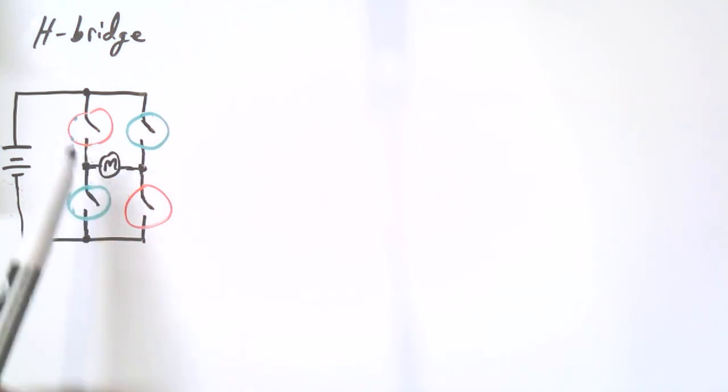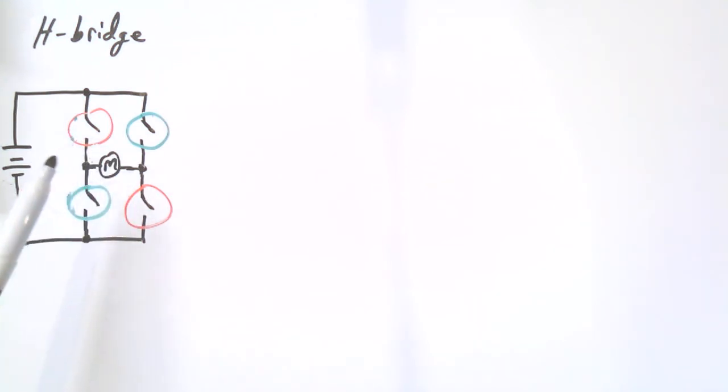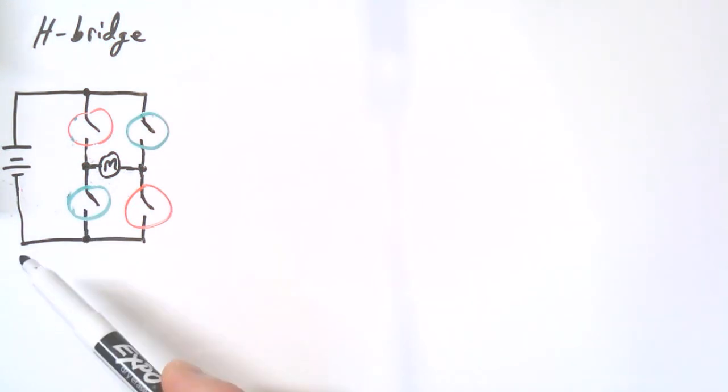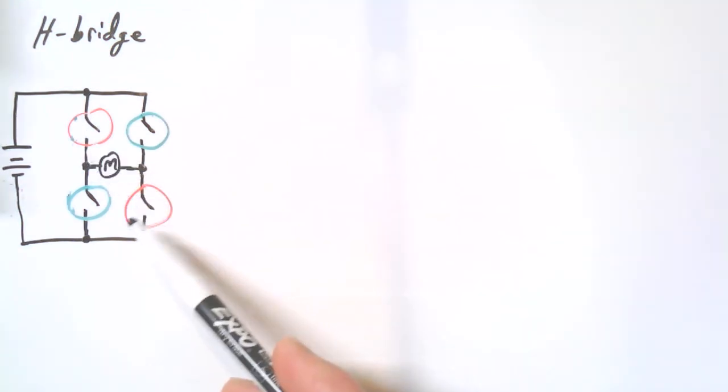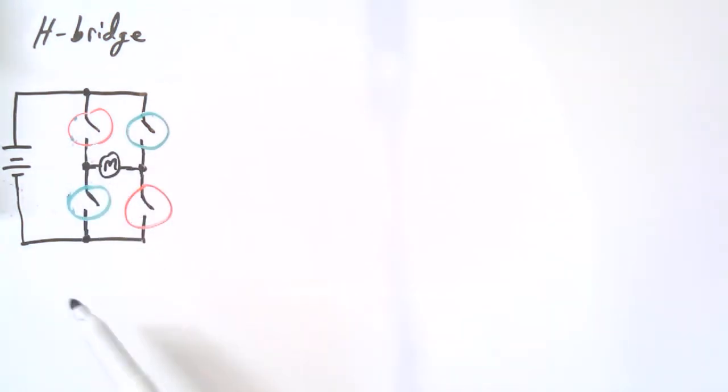But the red circle, don't let that get stuck in your head and reach for red contacts, because the standard, when you get to industrial switches, is that the red contacts are normally closed. So that's just a little heads up. It's something I've seen in the past. Those aren't red contacts. They'll all be green contacts when you're attaching them to your industrial switch. But yeah, it's an easy way to implement a forward and reverse scheme for a motor.